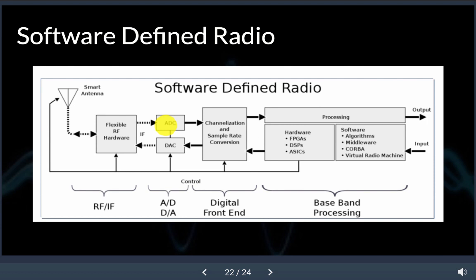You can keep trying to play with the software. You can shut down the software you're using, bring it back up and keep trying it. Most of the time, you're still going to have that problem. The way to clear probably 98% of the faults with these cards is to shut down the server they're in, remove power and remove RF from them for a few seconds, plug it all back up, power it back up, and it will fire back up. 98% of the time it's going to work for you after that. So that's what they're susceptible to. Whenever you get those errors, that's usually the fix.